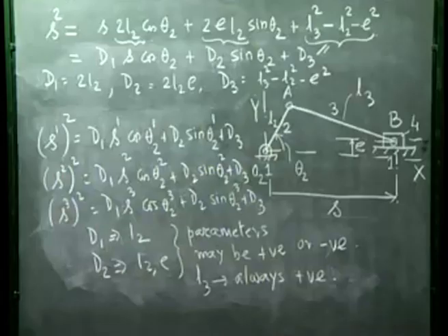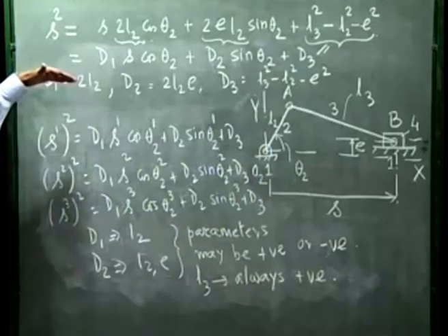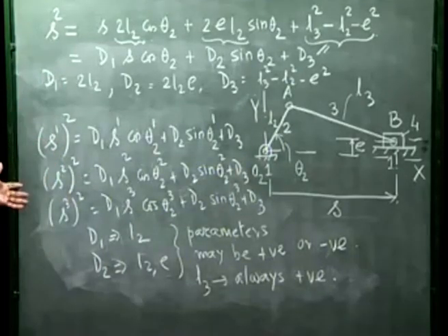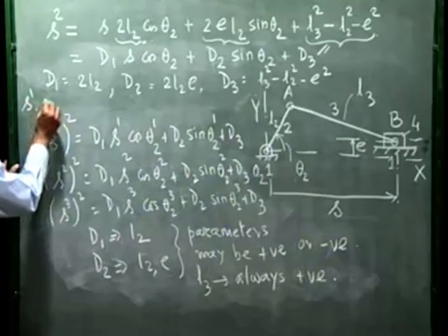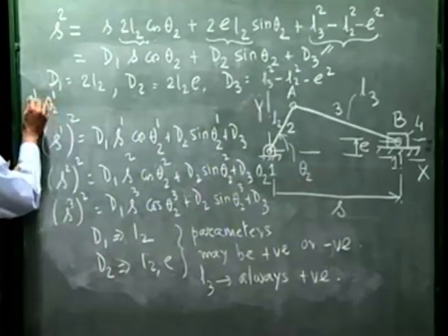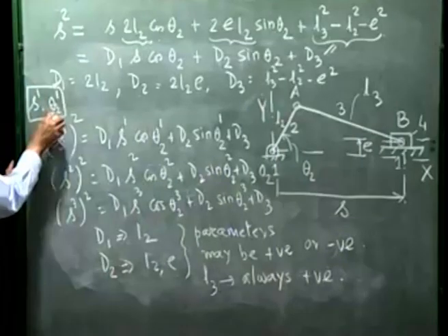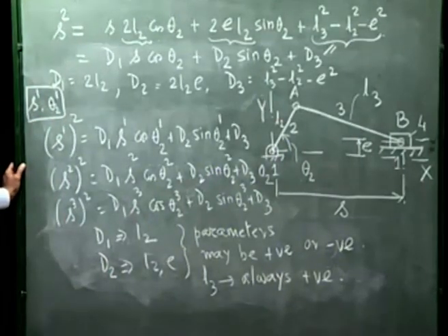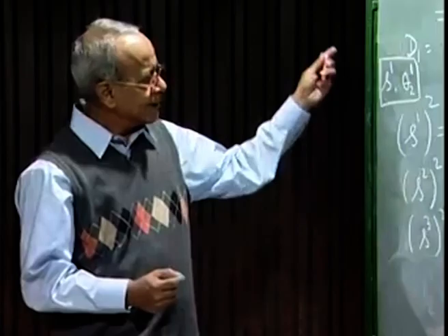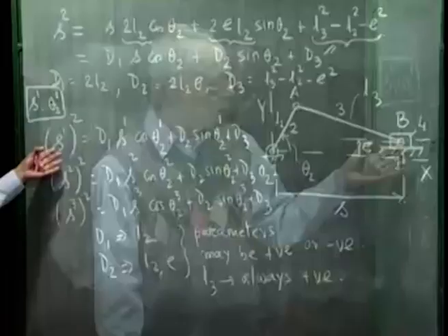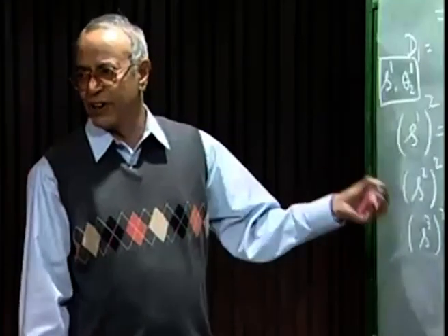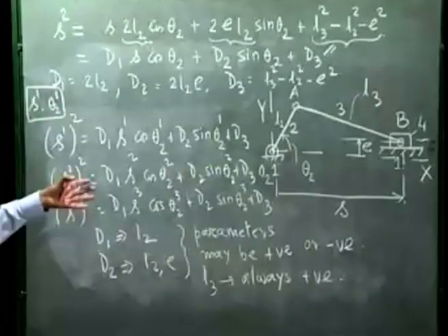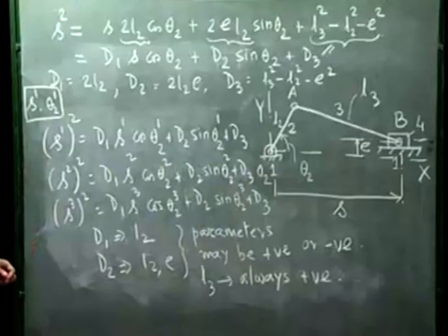The thing to note is that if we want to extend this to 4-position synthesis, that is to generate 3 pairs of coordinated movements, we have to leave either S1 or theta 2 1, which we assumed, as an unknown to be determined. The resulting equations will no longer remain linear in the design variables, and that adds to the difficulty of solving this set of nonlinear algebraic equations.